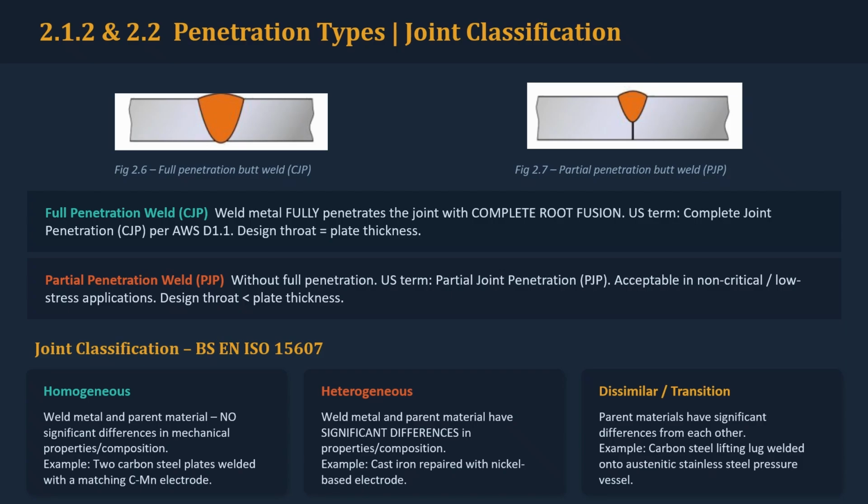This distinction becomes particularly important when considering welding procedure qualification, metallurgy, and the effects of the welding thermal cycle. For example, welding carbon steel to an austenitic stainless steel is not simply another carbon steel welding operation. The materials respond differently to heat, have different metallurgical characteristics, and may require special procedure controls. As an inspector, your job is not to redesign the joint. Your job is to understand what the design and qualified procedure require, and then verify that the work complies with those requirements.